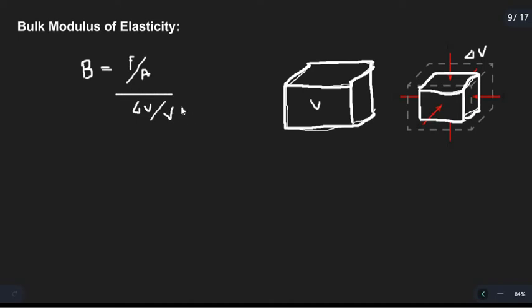अब एक चीज सुनिए, काफी बुक्स में they use a negative sign here. Why do they use a negative sign here? Because as the volume is being reduced, in the previous Young's modulus में क्या हो रहा था, आपका लेंथ बढ़ रहा था, यहाँ पे वॉल्यूम आपका घट रहा है. So you should use a negative sign, because इसका differential form अगर आप लिखे तो negative sign, as you are using a del, so you can definitely give a negative sign. Okay, now this minus F upon A, so whole del V upon V.